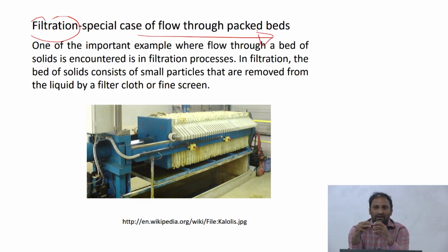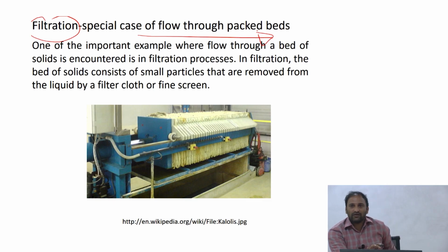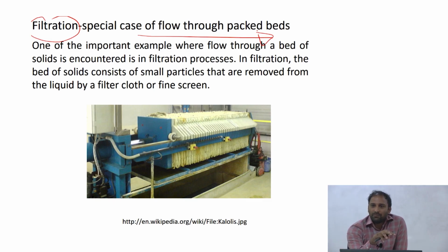On the strainer you have a solid bed, initially a clean cloth or something like that. At some point, as you start straining, a bed of solid forms, and the liquid starts flowing through this bed of solid formed on the surface. So we're going to talk about filtration at some point. Whatever working equation we develop for packed beds, we can modify to suit the need of filtration processes. We'll talk a little bit about that.